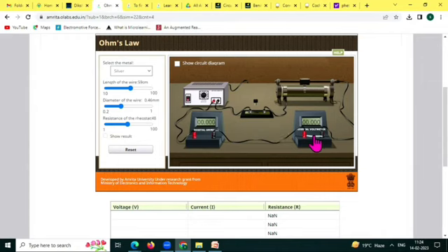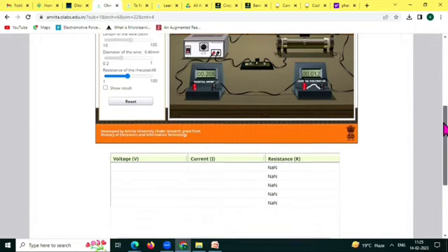The voltmeter will be connected across the unknown resistance. So, I have connected here. Now, say I am connecting it here. Now, it has been connected. If I connect it wrongly, it will not function, it will show. Now, I am switching on the plug, and now I have completed the circuit. Okay. So, now we can take our measurement.